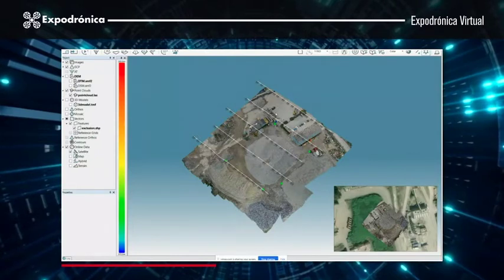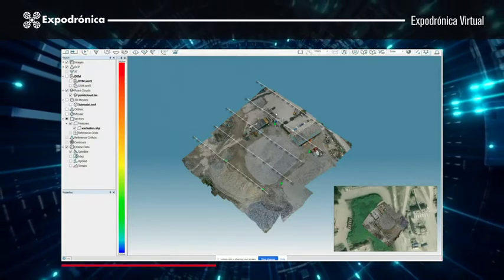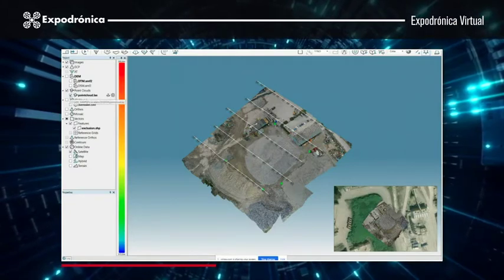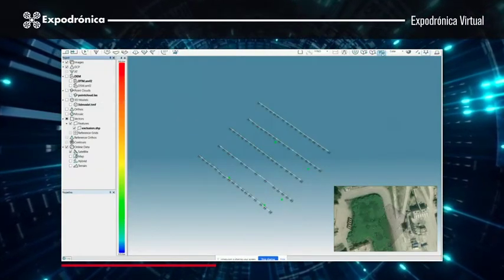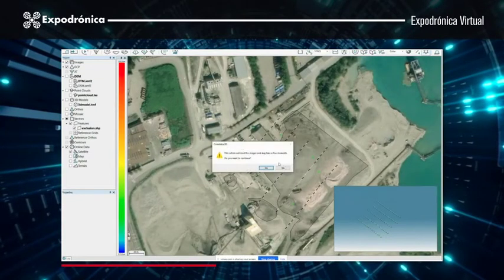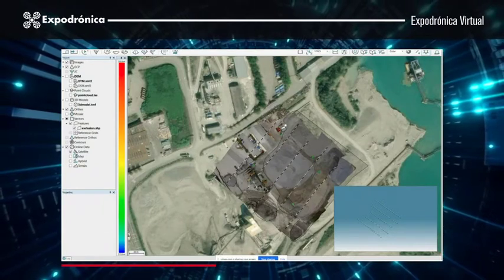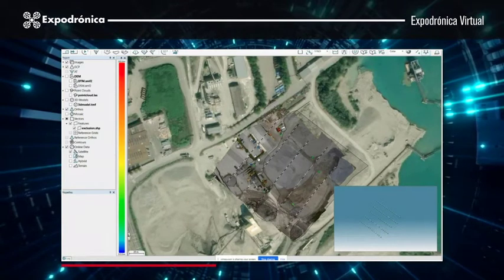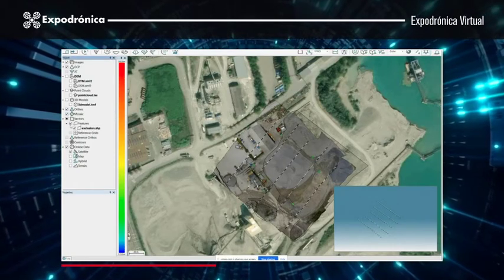Once the 3D data has been derived, the user can then extract some ortho photos. He can generate single ortho photos: for every input image, the software will orthorectify the individual images. And from those individual images, we will be able to derive a seamless mosaic, which is color balanced.